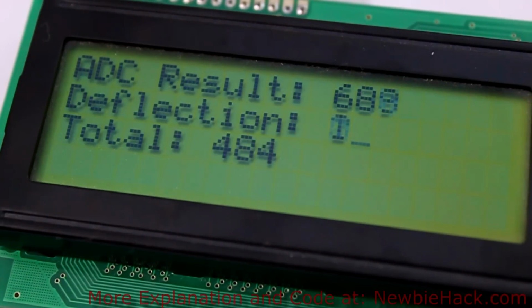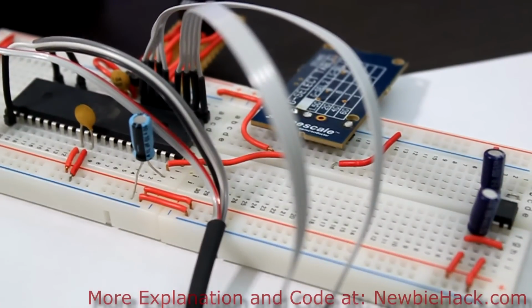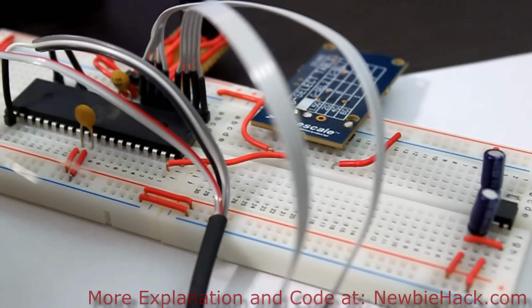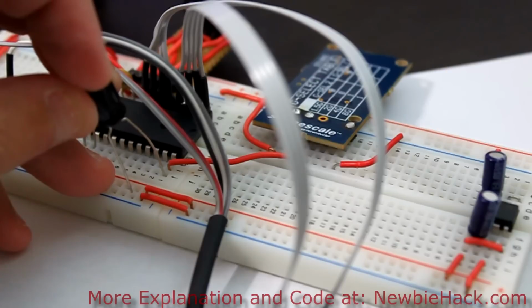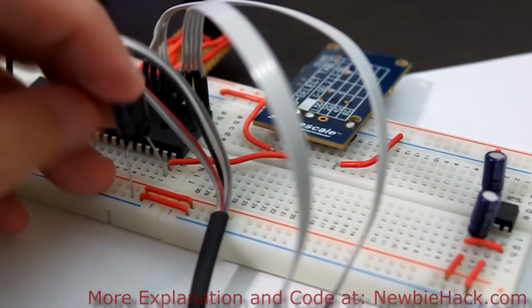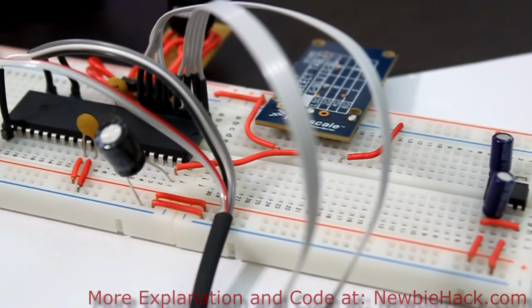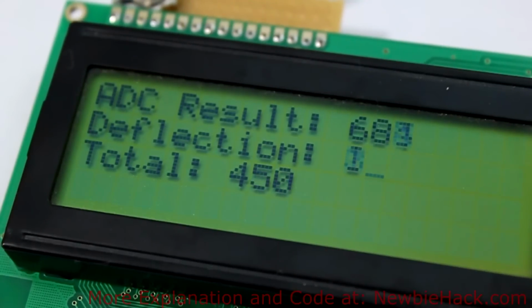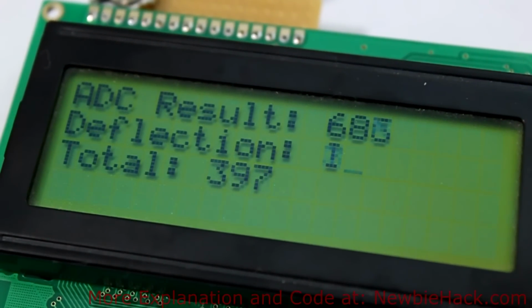Now let's try putting in the 100 microfarad capacitor. And I'm going to put it in the same way, positive side to the ADC pin and negative side to the ground rail. It's always good to confirm, because these capacitors can be destroyed if you put them in backwards. Plug it in. Okay, we're getting around 400, 450, 380. So we're getting an average of about 410.